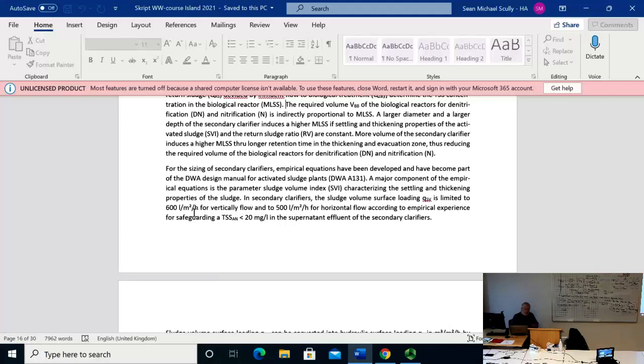And if you want to limit a wastewater treatment plant to that, you either need to have a big sewer system and big plants. The quotient between peak flow and average flow is of course lower than for a small plant. Because in a small plant, all the people have breakfast at the same time, and everybody lives close to the wastewater treatment plant. So the water is rapidly there.